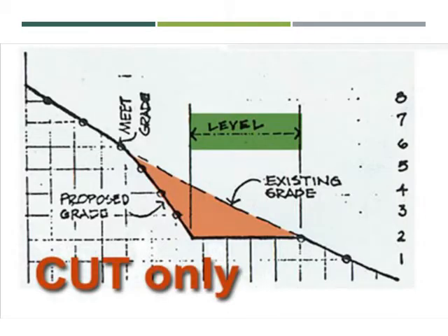They get closer together here because it's fairly steep. In section, you can see the same concept. These contours that used to be out at the existing grade are pulled back to the back side of the terrace, creating a steeper grade on the back side of the terrace and a flat surface for the terrace itself.